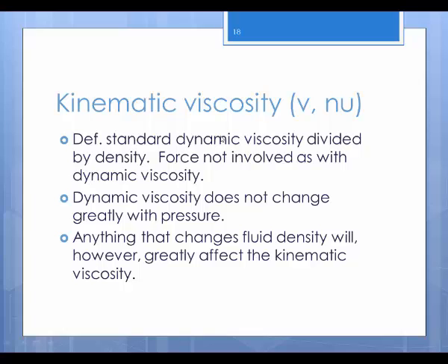So kinematic viscosity is just the absolute viscosity divided by density. That's really all that it is. There are some other important things here, but one thing you should think about is, if you know that absolute viscosity changes with temperature, and you know that fluid density changes with temperature, then to know how kinematic viscosity is changing with temperature, you really have to track how both of those are changing. And kinematic viscosity is important because it shows up in a whole lot of equations. So that tells you it's an important quantity.